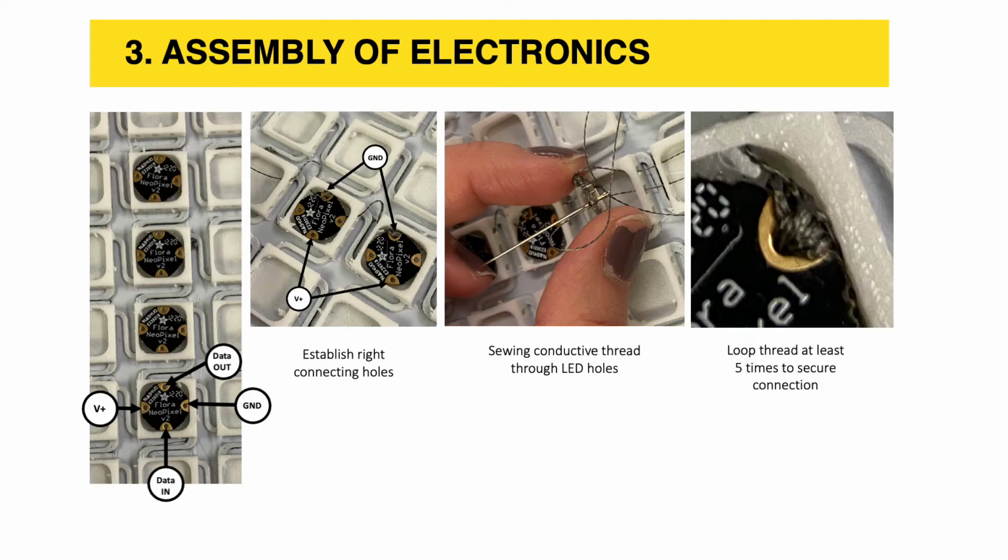We specifically decided to use LEDs which were designed for wearable applications, as they are easier to connect using conductive thread with their specific pinholes. Once you have placed each electronic component into its designated gap in the tile, you can simply thread the conductive thread through each RGB LED, and to ensure there are no issues with short circuiting or cross wiring, we insulate the conductive thread using clear nail polish, which works very well as an insulator for conductive thread.